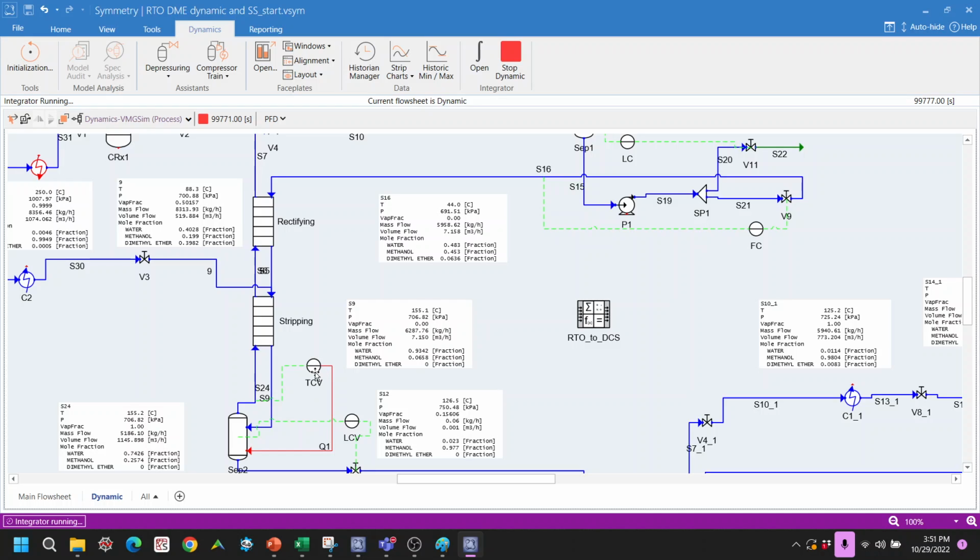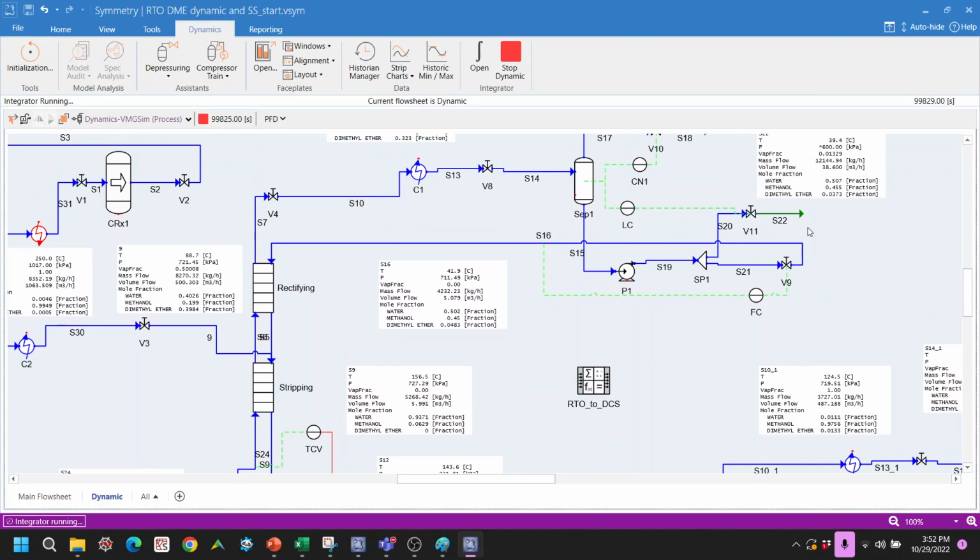So these three, bottom temperature, reflux, and the pressure of the column, become your independent variables, and you can model the performance of this column. You can model the yield of distillate, the flow rate of the DME, and the purity of the DME using these three independent variables. Then you can see which areas you are confident in, and use that specific area to do the optimization in Excel, the one that we did in the hydrocracking unit.